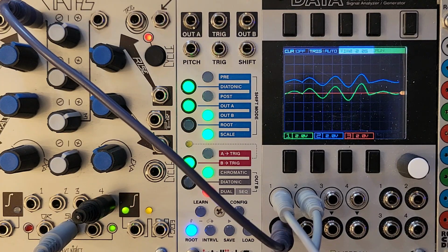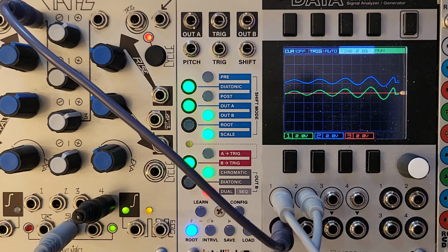But let's look at one of those bipolar to unipolar examples. By now you might recognize the output of the Nonlinear Circuits Triple Sloths. If not, I've got a whole video about it, but the X outputs from it can vary from about -2.5 to +2.5 volts. One thing that I tried to do early on in my modular journey was to control VCAs with it, and I didn't understand why it was just silent most of the time. Now the answer's obvious. You can't open a VCA negatively, it needs positive voltage. What I really needed to do was add some voltage to it so it wouldn't go negative, and then scale it up or down to give it the range that I want. And that's more or less what we're seeing here, with the original in green and the offset one in blue.